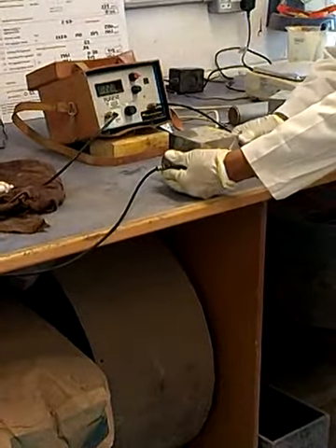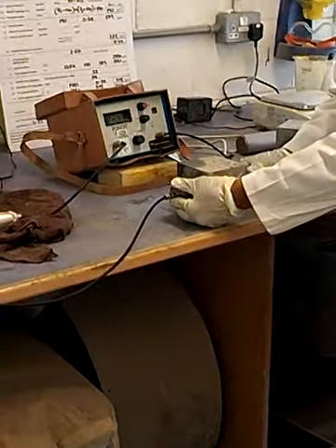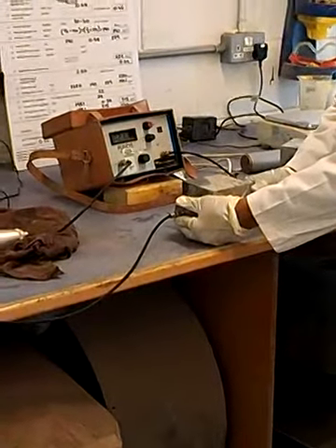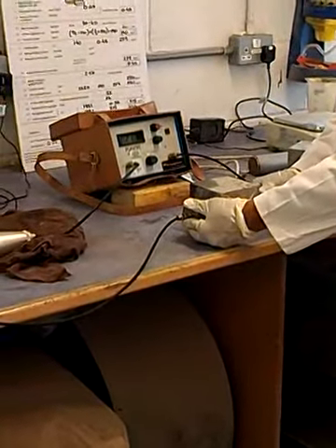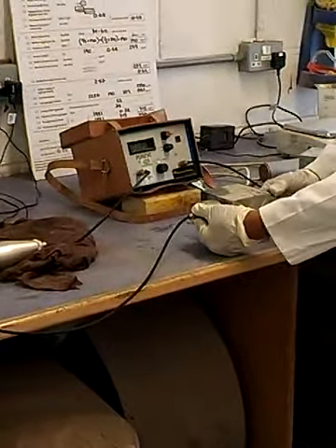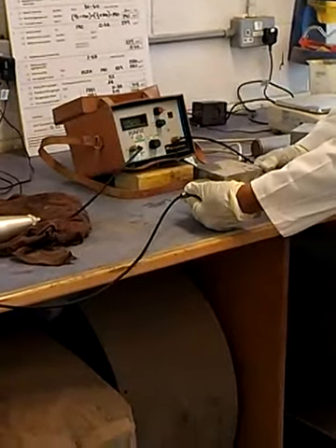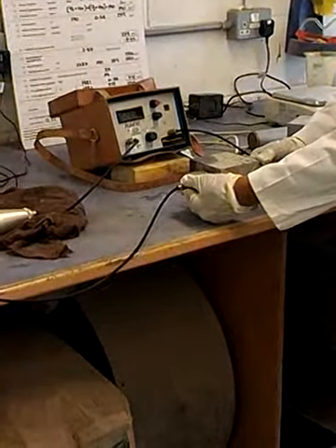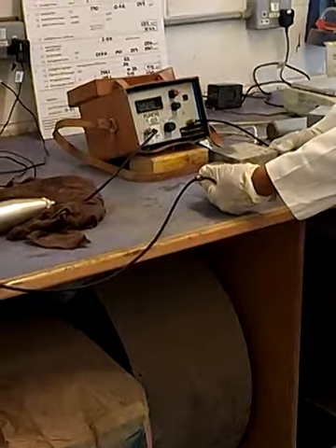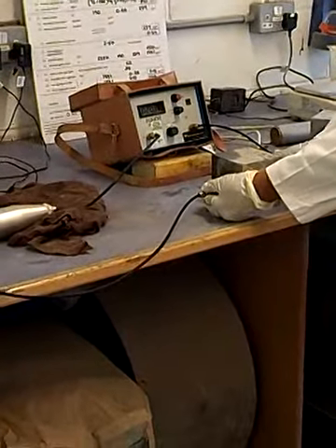Once you put the transducers opposite to each other, press it. Then you'll get some readings over there. What's the reading now? 21.1 microseconds at the center. Then move it to the top side, but not to the edge, just 10 millimeter below from the top side. Then get the second reading, that is 20.4. The third reading is 20.9 microseconds.